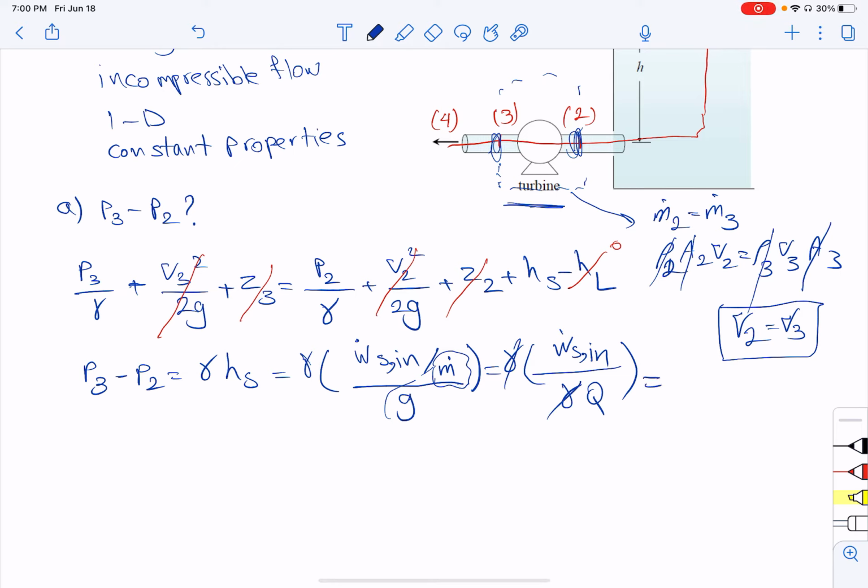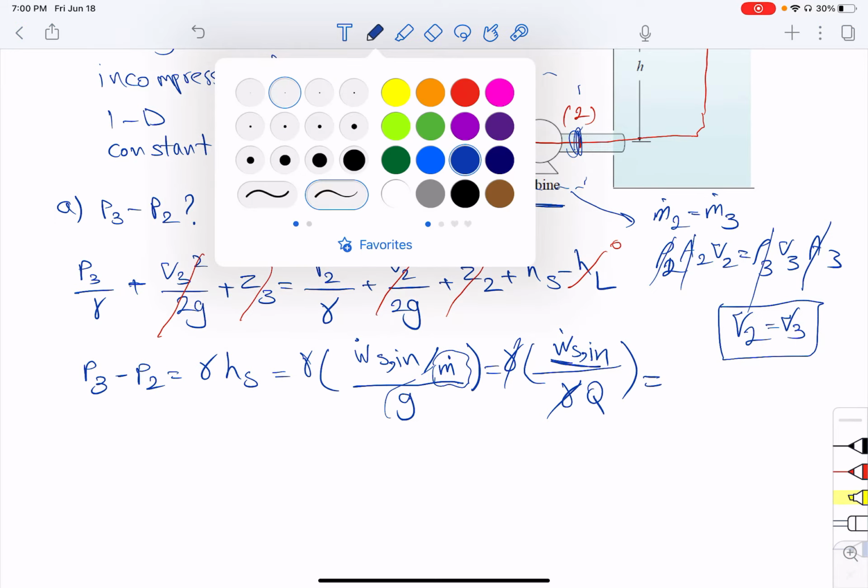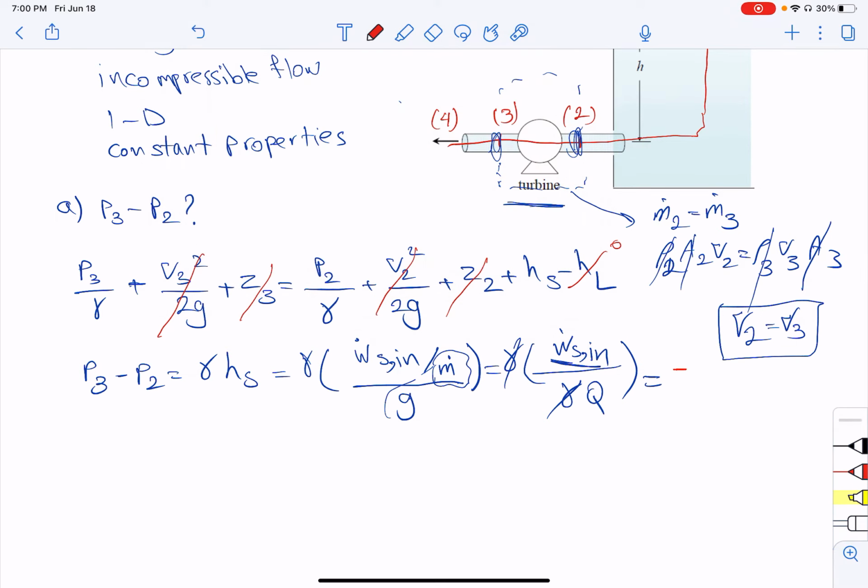From the lecture, if we have a turbine in the control volume, the sign is going to be negative because it is associated with the shaft work out of this control volume. So for this W dot here, we put a minus sign, right? And the value is 2500 kilowatts.